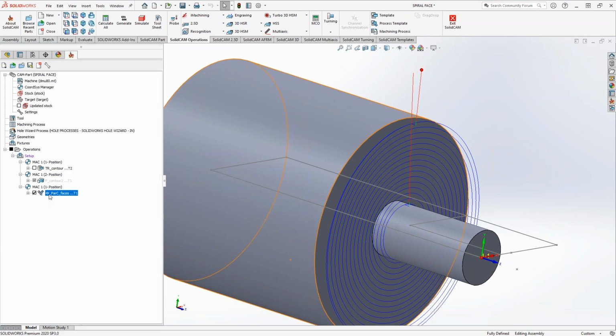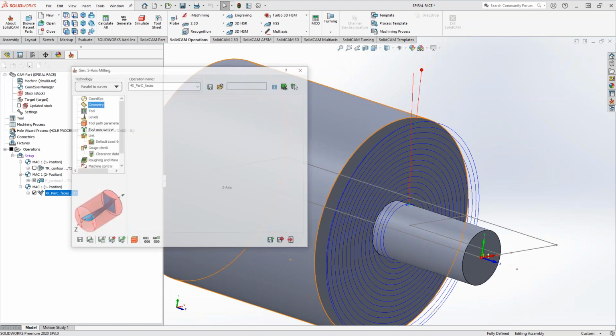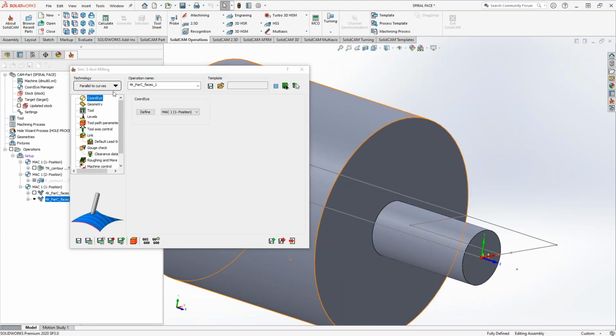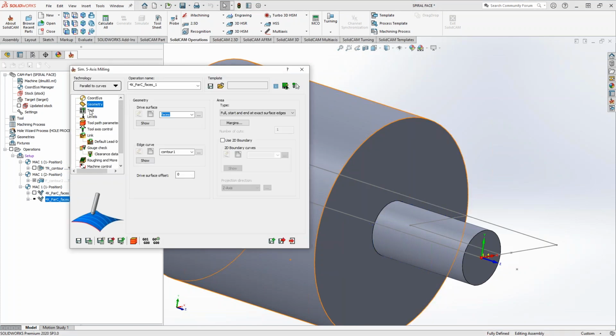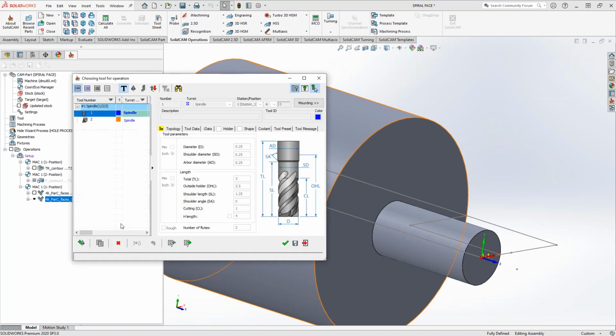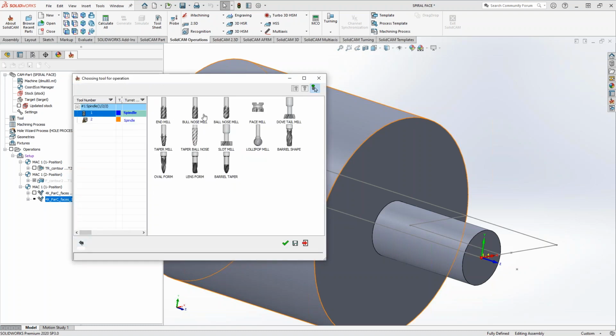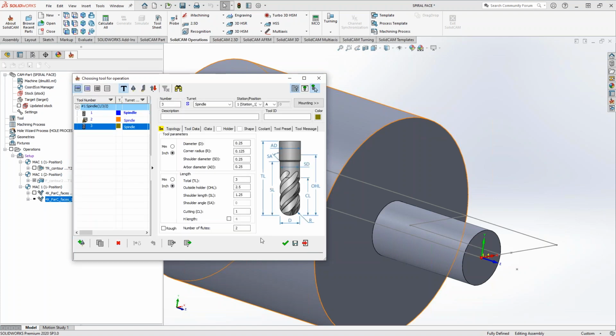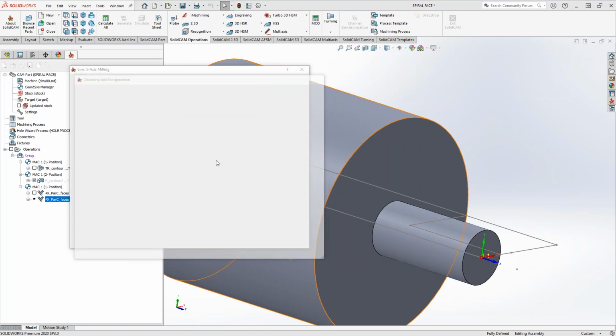So let's do a save and copy. Once it brings it up, there we go, save and copy. Okay, so we'll leave the tool path very similar. What we'll do is we'll just change the tool to a ball mill. Let's just add a 1/4-inch ball mill, just the default one. Let's say it doesn't have enough reach. It probably does, but just in case.